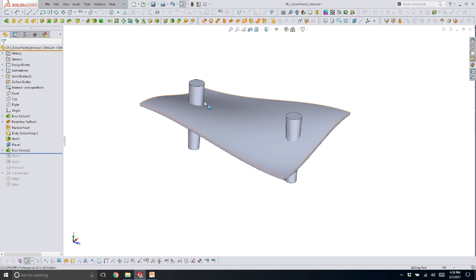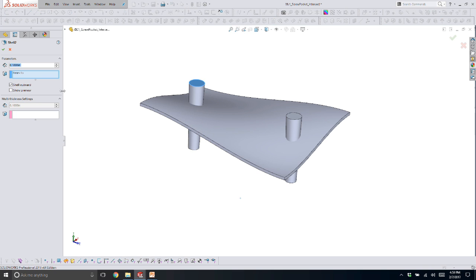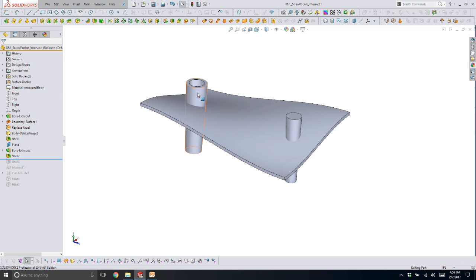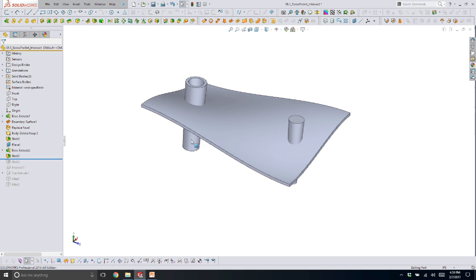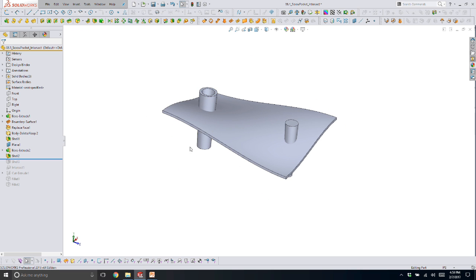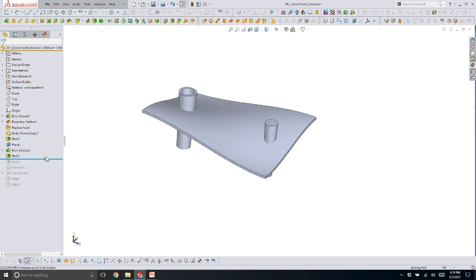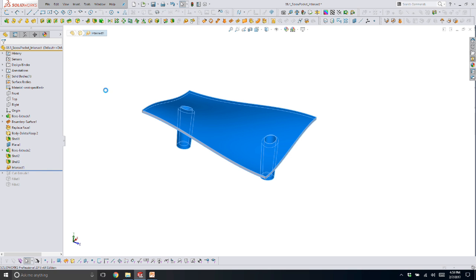So think of this as the cut. This is the negative space of the screw pocket. And then I'm going to shell each one of them individually, but I pick shell outward. So now what was my negative space is actually the negative space. So I'm using a solid to essentially cut what's not there. Because I have two screw pockets, I've got to shell each one individually. And then I used the new intersect tool. This was 2014, I think; it came out in 2013.